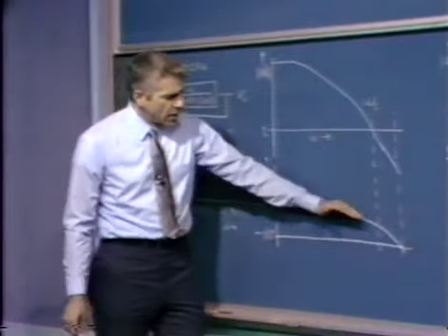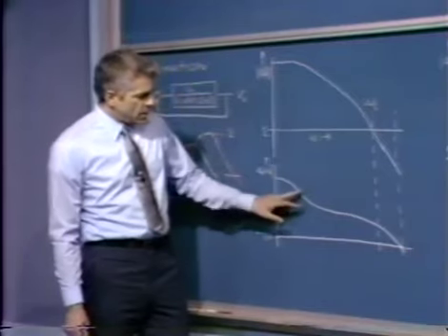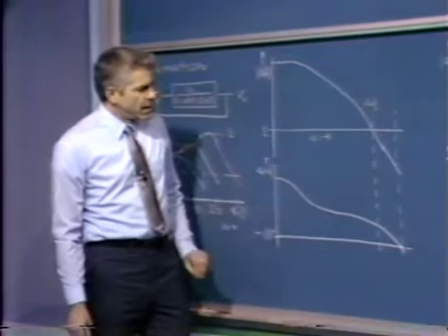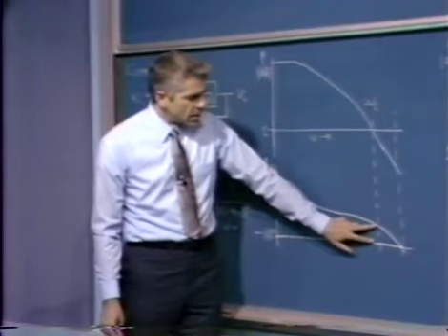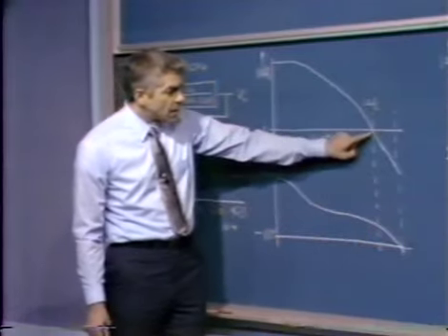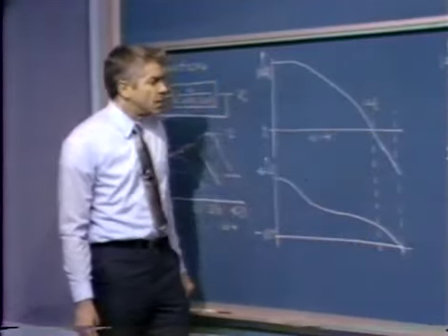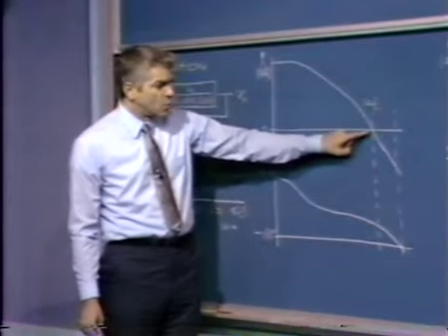If we have this sort of a well-behaved kind of a system, then in fact the Nyquist test simplifies greatly, and we can convince ourselves that providing the angle has not yet reached minus 180 degrees, when the magnitude has gotten down to 1, the system will be stable. And so here we've shown that situation. The magnitude of the AF product is 1.